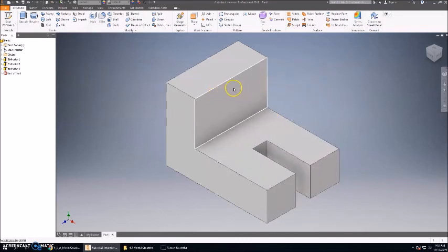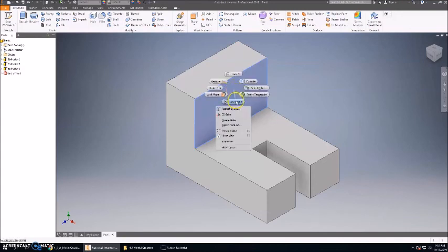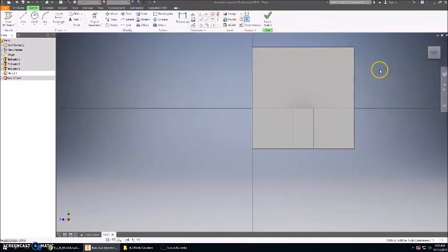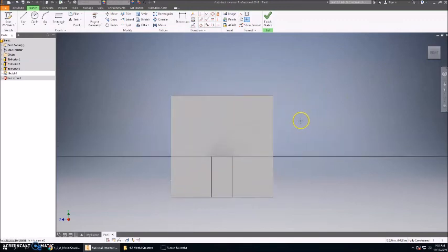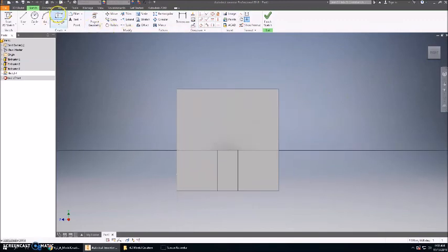My last subtractive portion is up here. So I'm going to right click, new sketch on this surface. I'm going to again push and hold with the wheel of my mouse. And I'm going to grab my rectangle tool one more time, starting on this edge, and you can see I didn't quite get the edge there. So I'm going to hit escape, and I'm going to come back here, make sure I've got that edge, and I'm going to draw a rectangle.